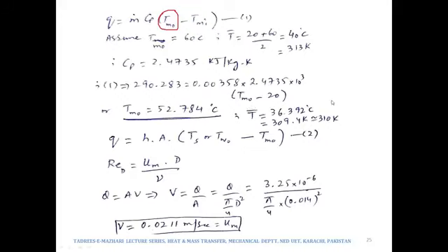Then we will adjust T bar. T bar as per this new value of Tm naught will be about 310 Kelvin instead of 313 Kelvin, right? Since we take the average of the temperature, the deviation between the actual value and the assumed value will not really make a very large difference unless we assume a value which is either very small or very high, right? Now, this is how we will find out Tm naught.